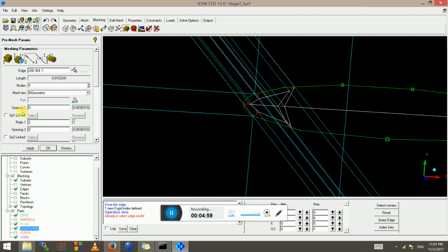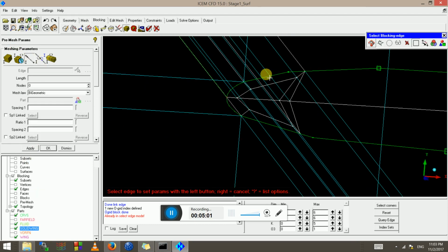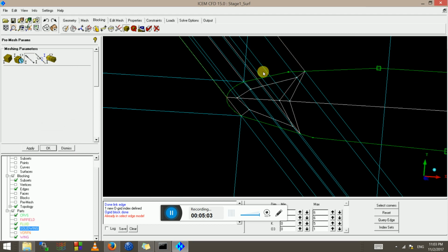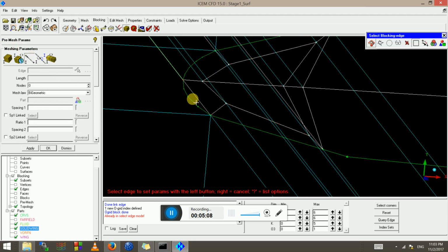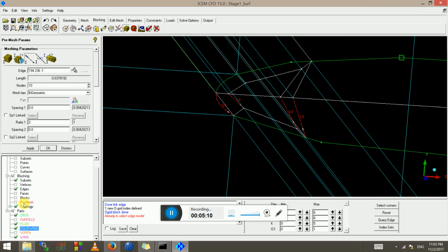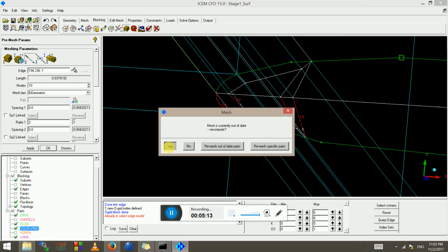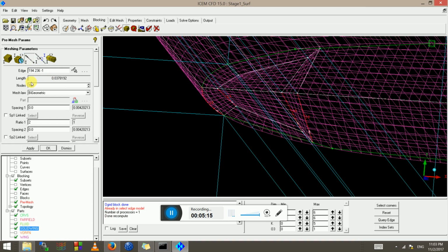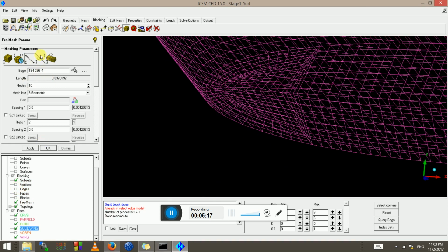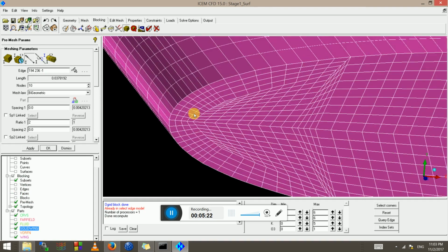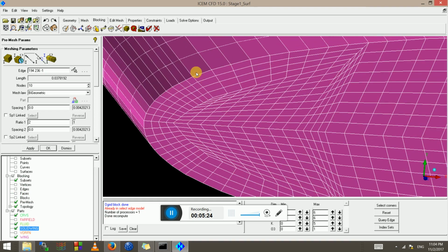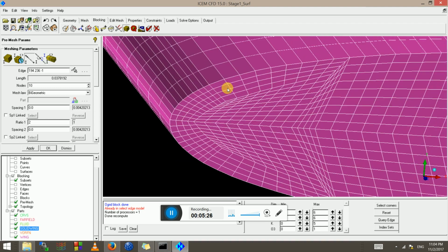And I have to give some new dimensions: this is 10, this is 10, so I'm quite happy with that. It's going to be a coarse mesh. If I turn off the edges now and go to solid view, you see the cells that were disoriented here have improved, and we can move around these vertices.